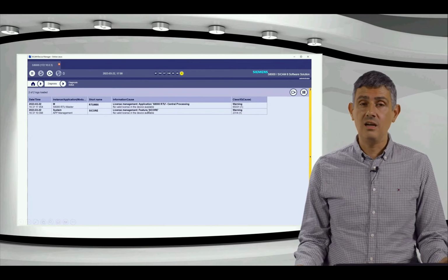Sicam HMI provides a web-based human-machine interface hosted in the Sicam E8000 or the Sicam S8000 automation units and can be used together with the S8000 functionality on the same device. Thanks to this solution, access to the different displays could be achieved through standard PCs or via inexpensive browsers such as tablets and small monitors, all while still following the highest cybersecurity standards. The graphic editor is fully integrated into the Sicam Device Manager, and no separate scalable vector graphic tool is necessary as in the past for creating this animated single-line pictures.